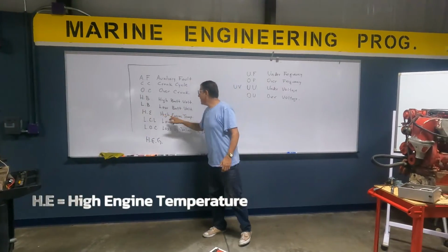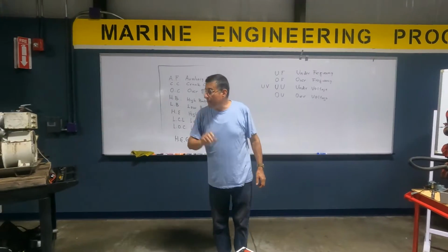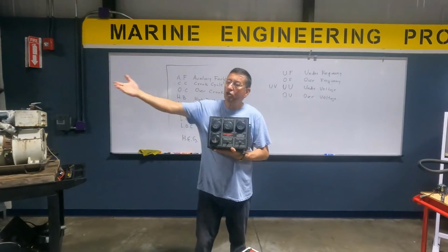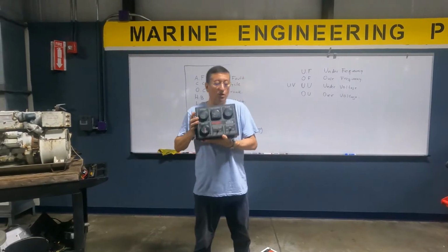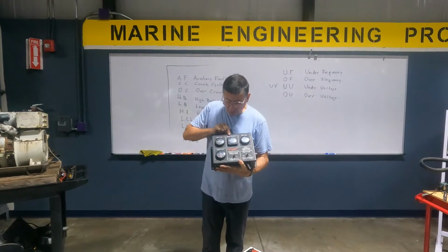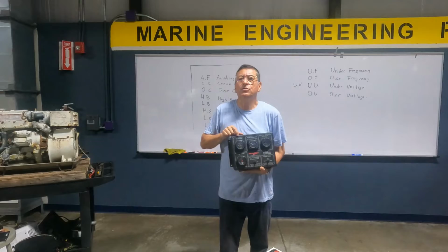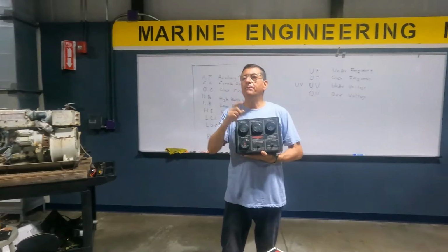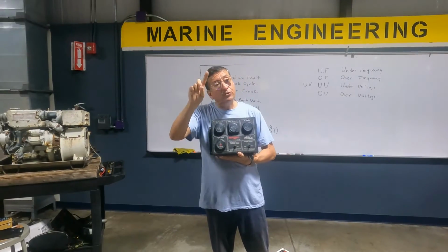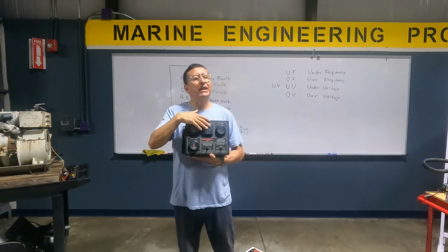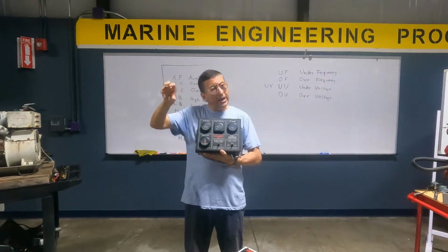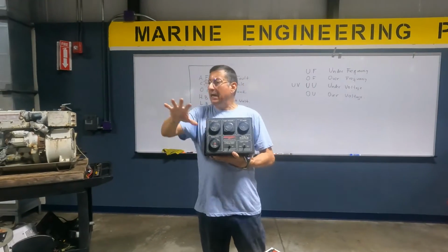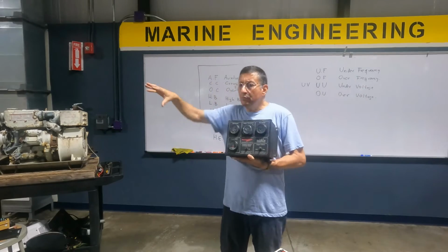When you have high engine temperature, ask the customer. Remember that in the main control box of the generator or the remote, you have engine temperature and oil pressure. Ask them, is the needle, the gauge of engine temperature, higher than the normal position? Yes, it's a little higher than normal. Okay, it's a problem related with coolant, thermostat housing, thermostat, radiator cap. Yeah, it's a temperature problem related with the engine.